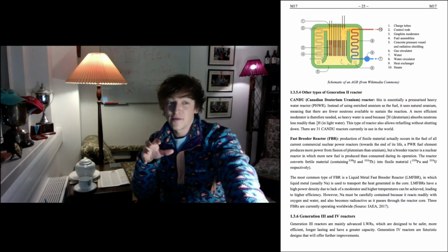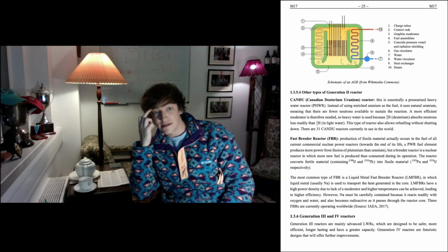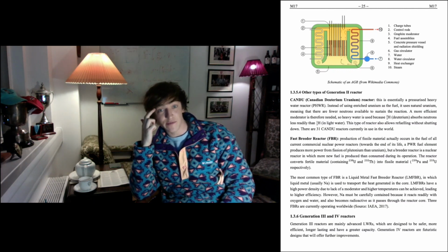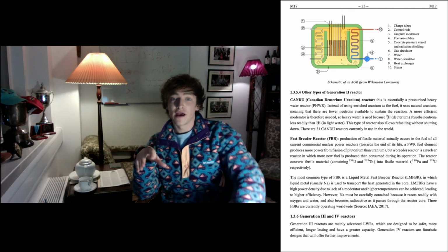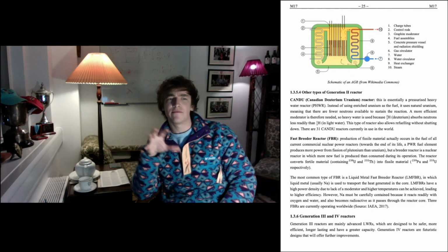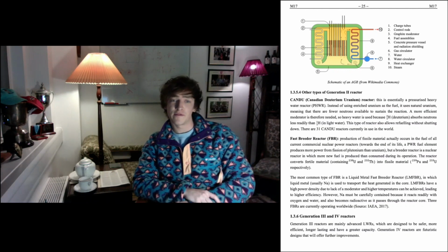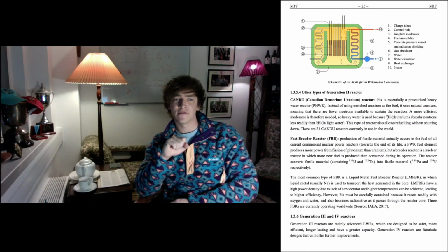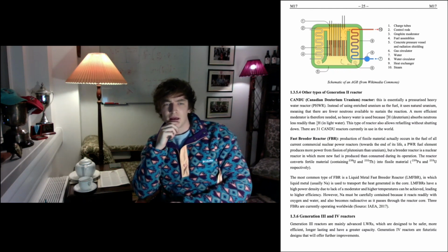They're much better in terms of thermal efficiency in comparison to PWRs, mainly due to the temperature difference between the steam and the cooling water. And these run at a much higher temperature than the old Magnox reactors, so that's going to also improve thermal efficiency. That was one of the main limitations of the Magnox, because they were worried about reactions at higher temperatures.